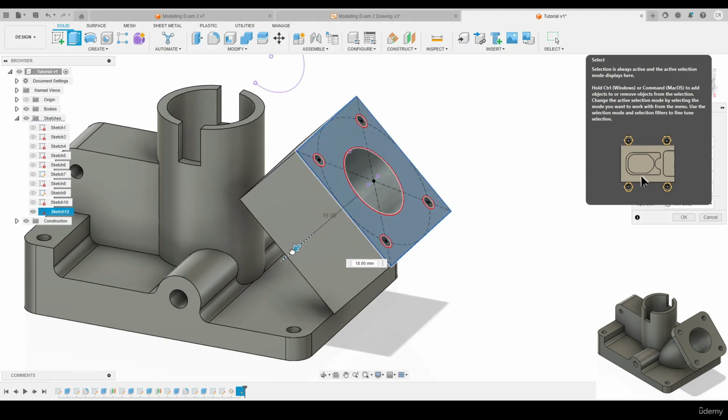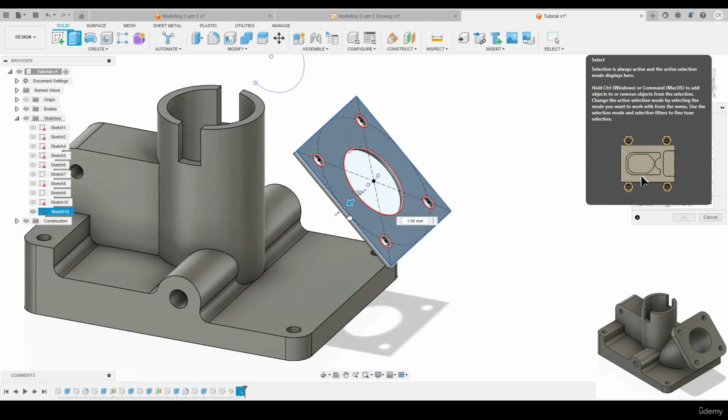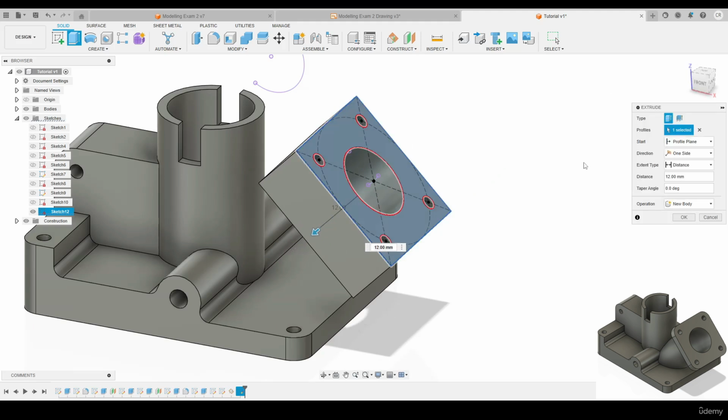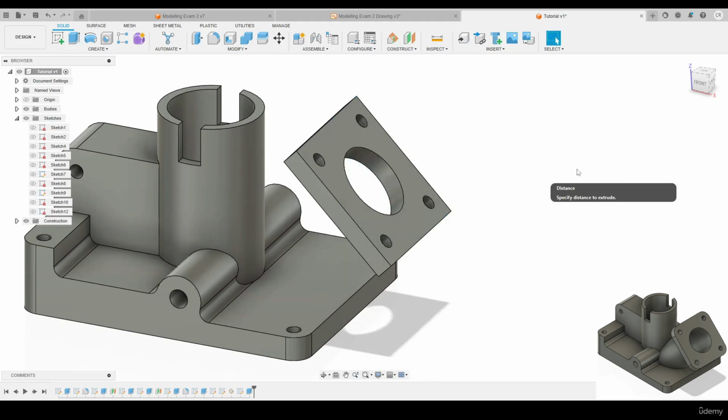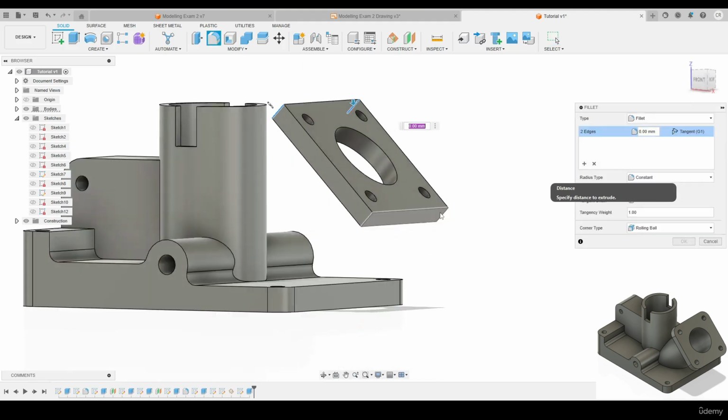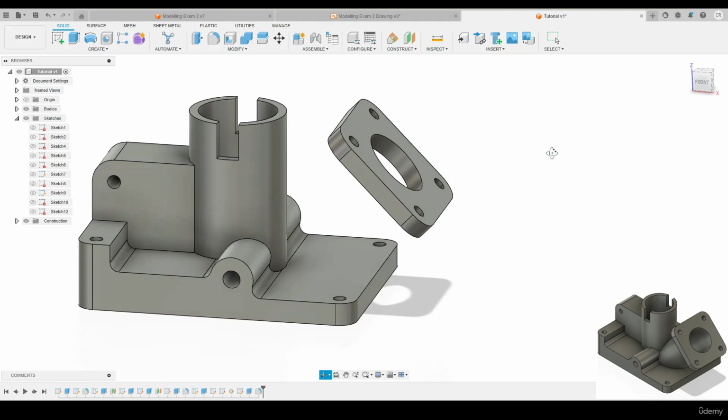I want to make sure that we're extruding in this direction, not in this direction. Okay, because when we put in our construction plane, it was this face of the flange. And so the distance, or thickness rather, of the flange, we've got 4 mil. Let's also go ahead and add in our fillets then. Let's press F on the keyboard. Select 1 edge, 2, 3, if I can get that one, and 4. And these have a radius of 5 mil. Press enter. Looking nice so far.